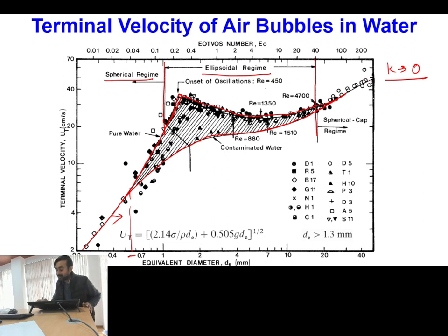And whenever I go to a very high value of the Reynolds number, the surface tension effect becomes so small that it is majorly dominated by the inertial effect of the flow. So again after this point the contamination is not making much change, and the two curves are following the same data set. But in this particular range where we have the air system, the presence of contamination will significantly control the internal circulation. So that's why we have different velocities.